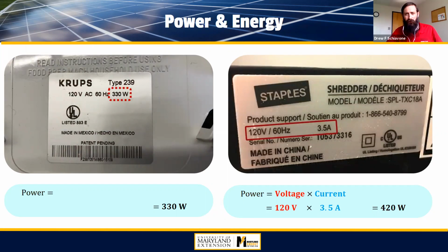Now I've also included another example on the right-hand side. In this case, there's no indication of the power. There's no wattage given. So what this requires is a little bit more work. We can clearly see that it's 120 volts is the voltage. And then if you look a little bit down the line, you'll see 3.5 amps, which is our current. So they do give us the volt and current. If you didn't have that, you'd have to go back and measure it manually with some kind of multimeter or something like that. But at least we have this printed on there.